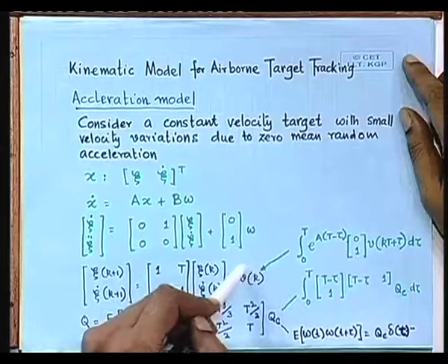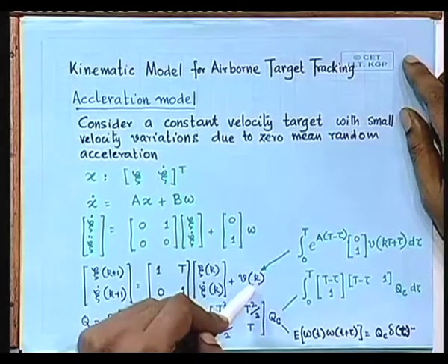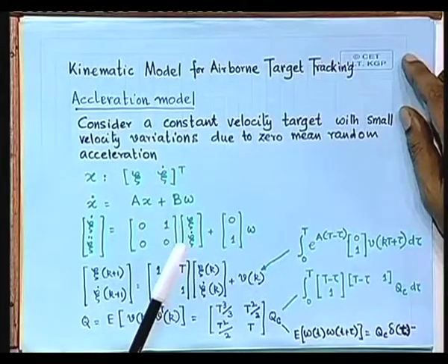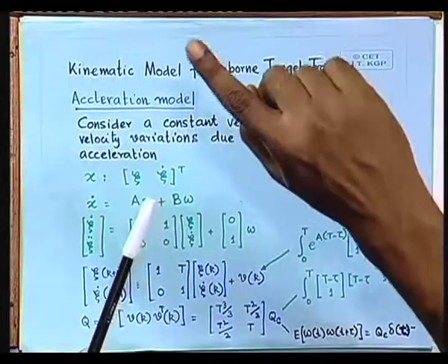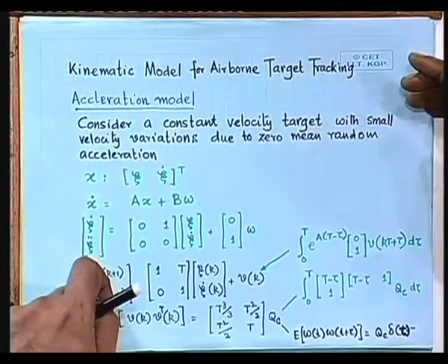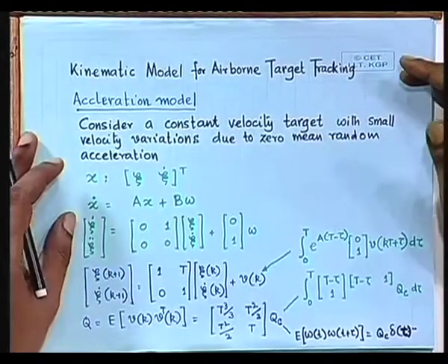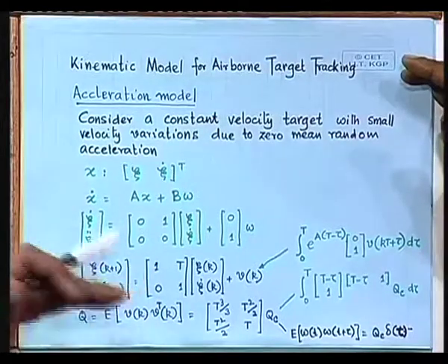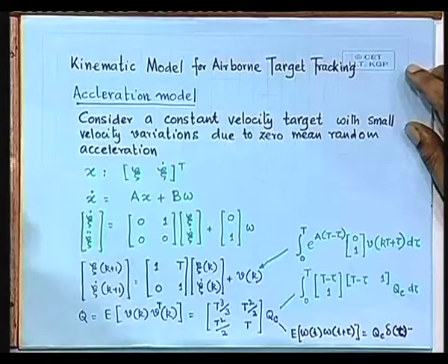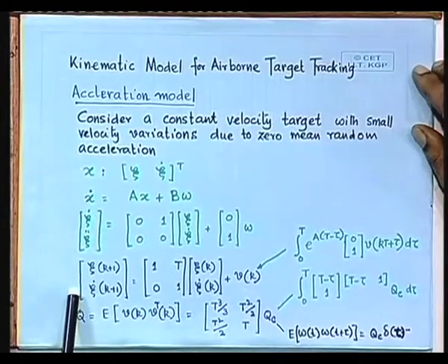That total accumulated effect you are approximating by a constant signal, as if at the kth instant you applied a constant signal Vk which remained constant from k to k plus 1 and produced exactly the same sampled value of this xi dot k plus 1, right. That is how you get it. This is what is known as a step invariant approximation of continuous time systems to get a discrete time model. So this is your discrete time model.